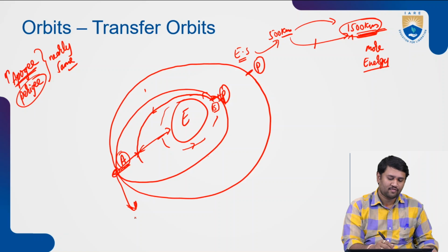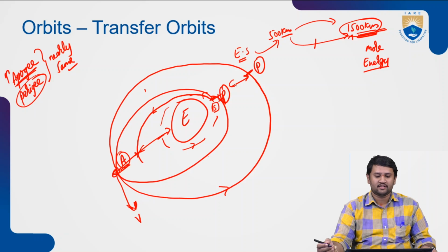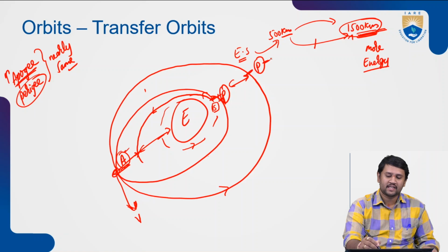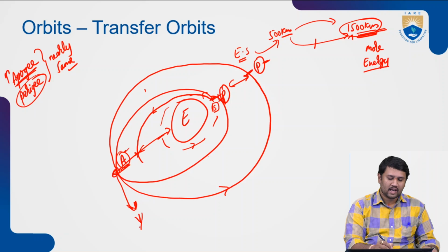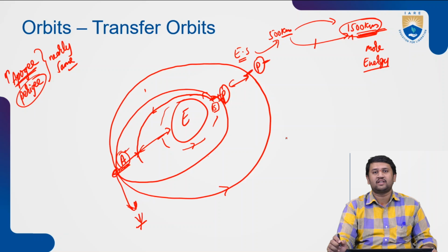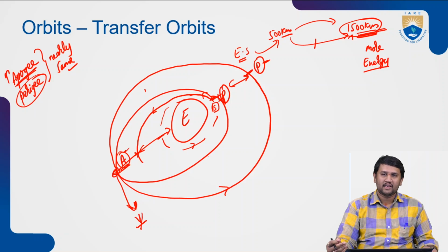You will be adding more velocity to increase its perigee to a certain distance or altitude. At the point where the apogee and perigee are nearly equal, we will end the addition of velocity so that the orbit is maintained as circular, right? The orbit is most probably circular, with only a difference of 1 or 2 kilometers, but the energy will remain at the same altitude.